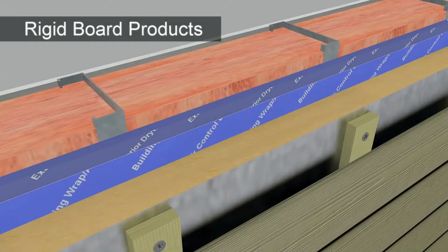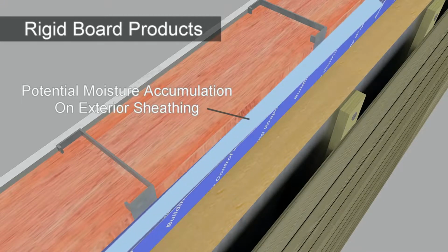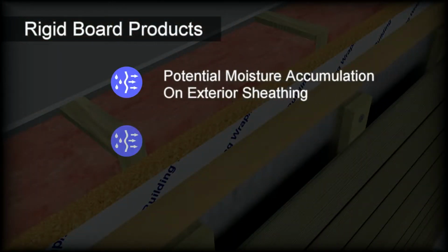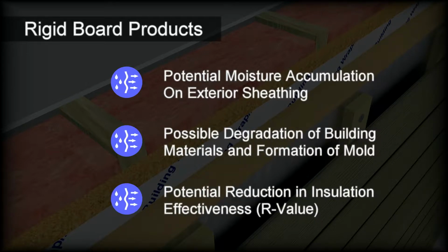Although achieving their thermal objectives, these products may hinder the drying capability of the wall. This can result in moisture accumulation between the exterior sheathing and the rigid insulation, which creates an environment for degradation of the building materials and mold formation. In addition, once wet, some rigid board products may not completely dry, thus negatively impacting their R-value performance.